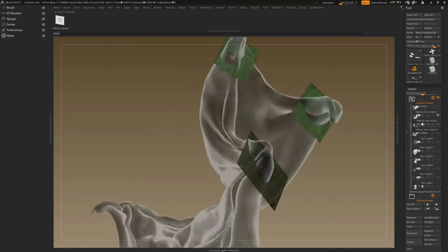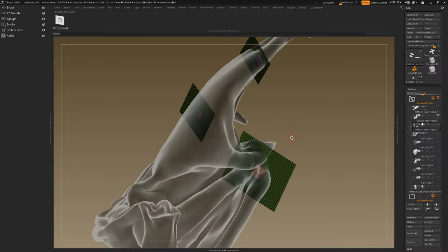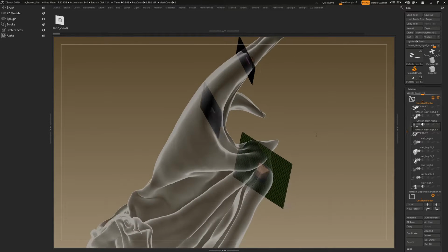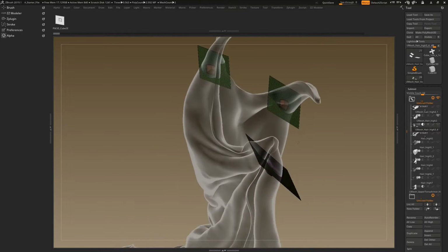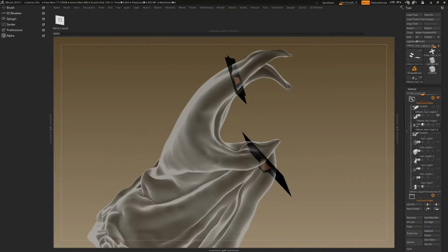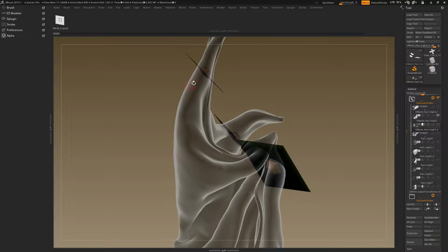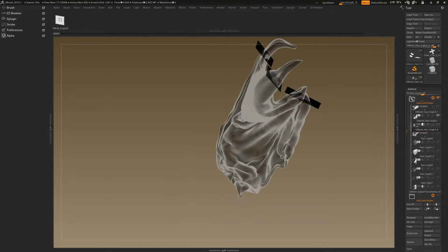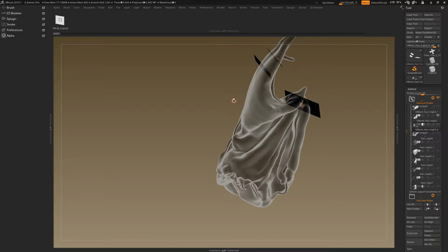If you guys ever get to the point where you're engineering models for somebody else, the worst thing you can do is alter the artist's vision. But there's a lot of times where you have to make minor edits to just make them functional. This one in particular, we had to thicken the cape quite a bit. We thickened it mostly on the inside, so we were able to maintain the silhouette. But there were a few areas that we had to close up or thicken, so that they were printable, not even castable, but printable.